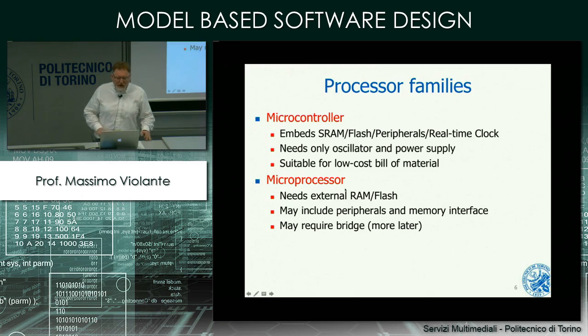The microprocessor, you have the CPU within one chip, and maybe a few other elements like, for example, the I/O interfaces. So if you think about the reference architecture, we draw a line around the CPU and I/O, and they are the content of the microprocessor. This is not enough for operating. You need a place to store the instructions, you need a place to store the data. And these are additional components that you have to place besides the microprocessor, okay?